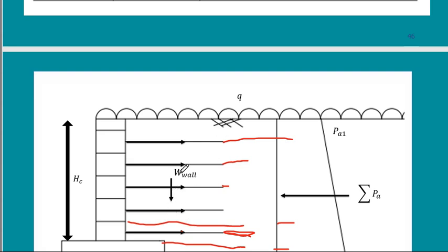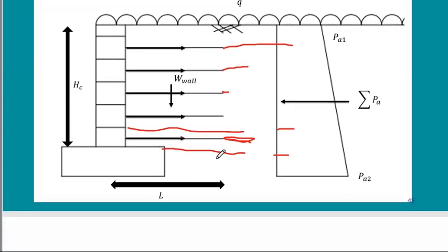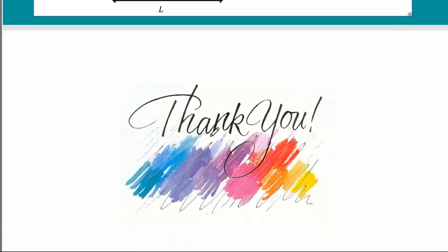But if I am designing the external stability, maybe I would need both the same, or maybe those at the bottom to be longer. So you design internally and externally and put the amount of the length of the reinforcement that you need in your wall.